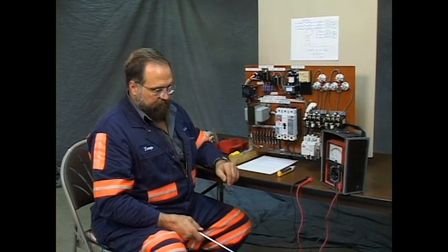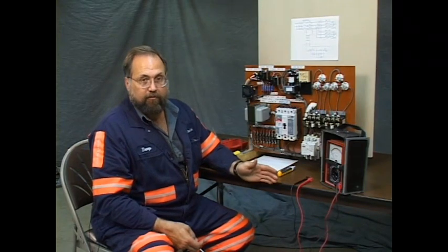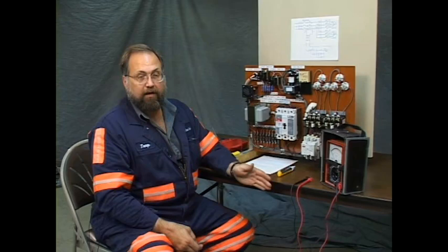Now people would think that you could use just a snap switch, a switch that would remain closed. When you want to start it, you close the switch and it remains started. But there's a problem with that. On a motor control circuit, you have a thermal overload. If you have an overload, draw too much current, before you damage the motor, the overload opens.